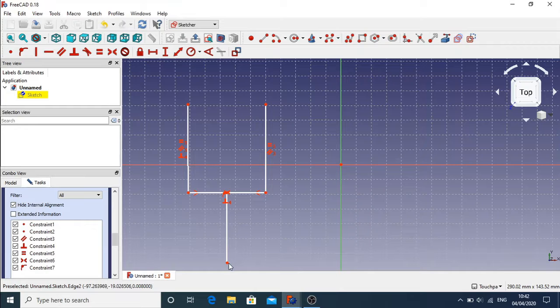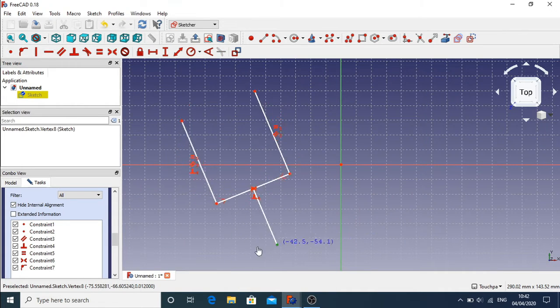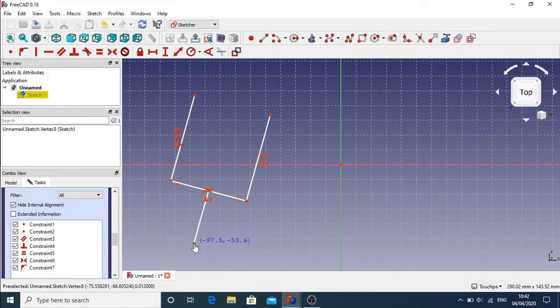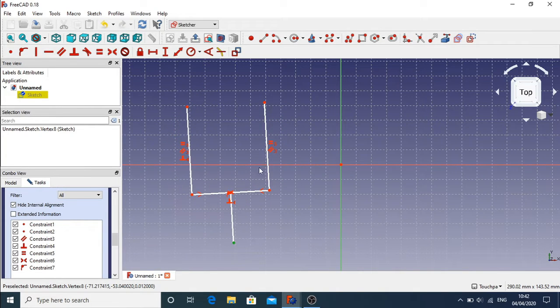So I haven't had any line datum constraints yet, and it's best to use geometric constraints because you end up with less on the page and things keep in proportion with each other and in symmetry. So when you have more datum constraints, things start to get messy. You can delete one which has an effect on all the rest, and it can get quite confusing.